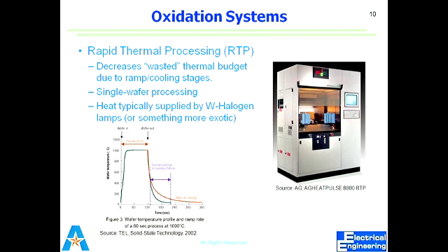The temperature to which you can go after you deposit layers on the silicon substrate. Like once you do metallization, you can't go on to higher temperature processes. So once a particular layer is grown, your thermal budget keeps shrinking down. Like you've used up that much, you can't go beyond say 300 degrees.